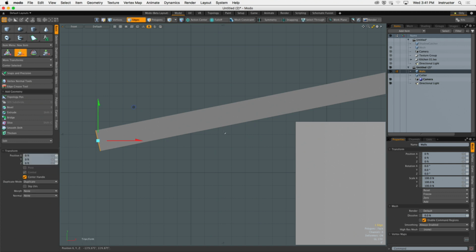We're going to use the move tool for this operation. Before I change my settings a little bit here, I want you to notice the orientation of the tool handles. Right now, they're aligned globally to the XYZ axis. Y is up, X is left and right. It matches our compass in the lower right of our viewport perfectly. Well, I don't want my tool handles to match the global orientation of the XYZ axis. I want it to match the local orientation of that polygon.